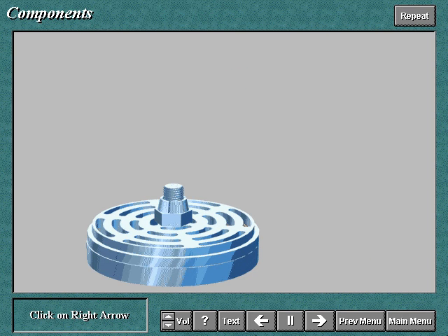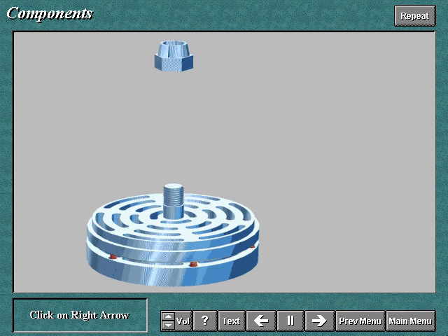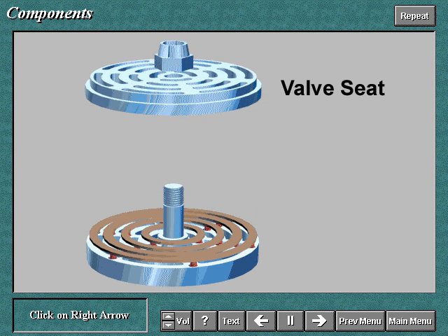All valves used on reciprocating compressors are made up of four basic elements: the valve seat, valve plate, springs, and valve stop. The valve seat is the circular component through which the flow ports are opened. It is sealed by the valve shutter. The seat and valve shutter together mechanically support the pressure differential.